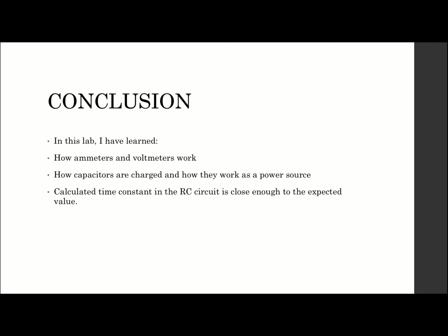In conclusion, in this lab, I've learned how ammeters and voltmeters work, how capacitors are charged, and how they work as a power source when they're connected with a light bulb. And I also found that my calculated time constant in the RC circuit is close enough to the expected value.